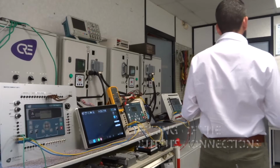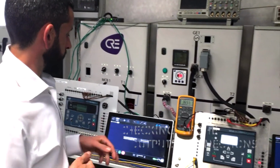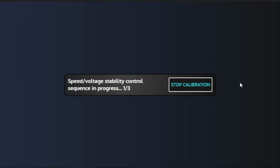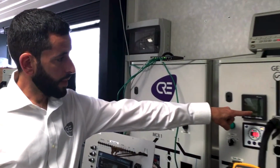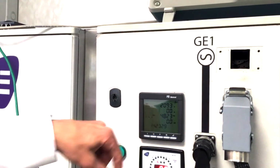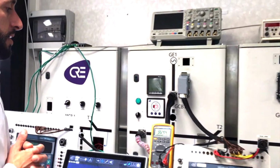At this moment, there is a first checkup to see if the outputs are connected. Step 1. It will also verify the stability of the genset and the voltage and check if EasyCalib can run in this situation. We can look at the frequency here. See that this is not really stable. Actually, this is something that I made on the wire to create this instability.